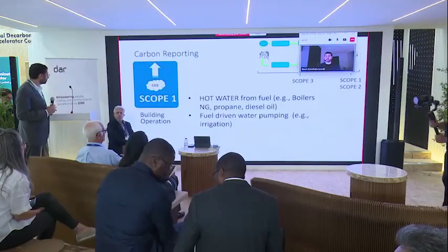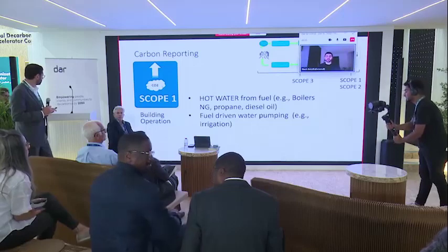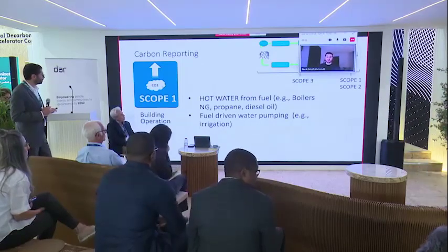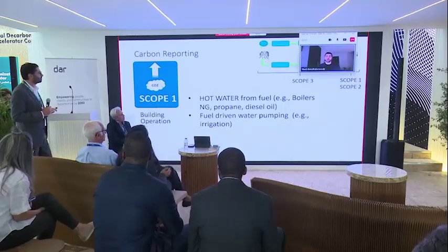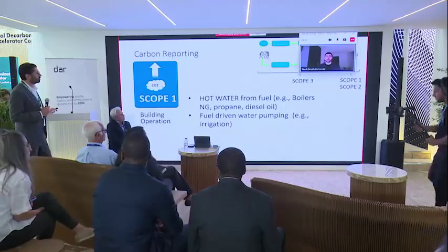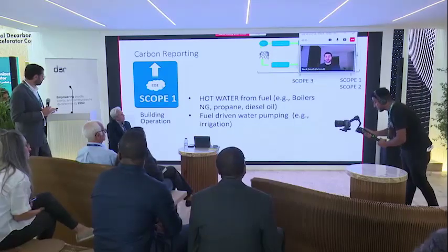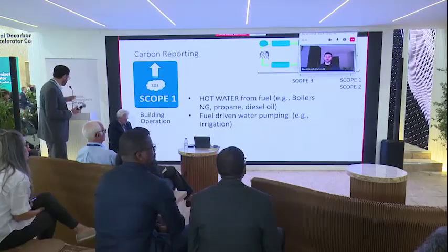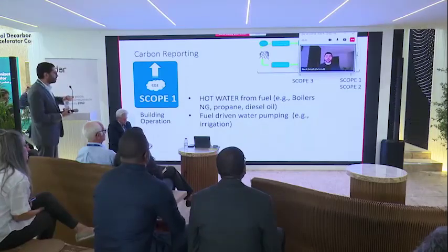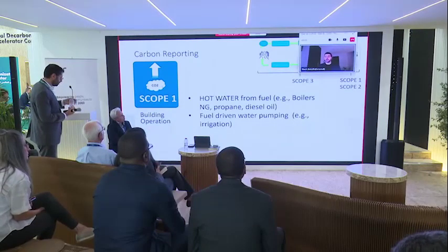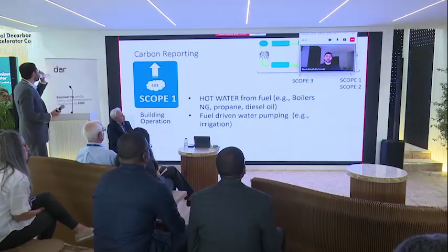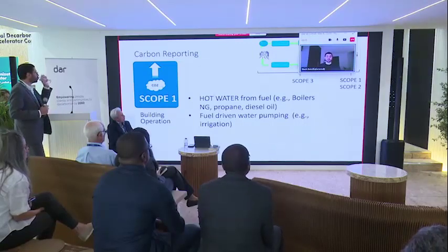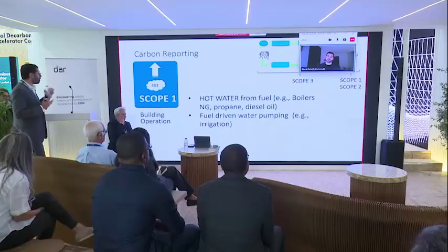What we want to consider is the types of systems and the fuels that they may or may not need to actually consume. On a hot water standpoint, can we heat water to the standards needed within the building using alternatives other than natural gas, propane, or diesel? Are there ways that we can tie it into other heat pump type systems where the fuel mix is a bit more environmentally friendly? Is it even needed? Can we shift to an electric driven system?